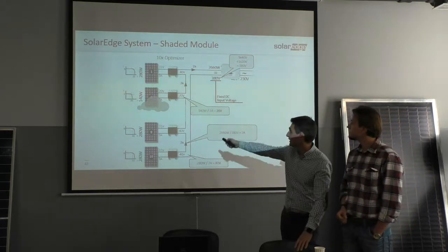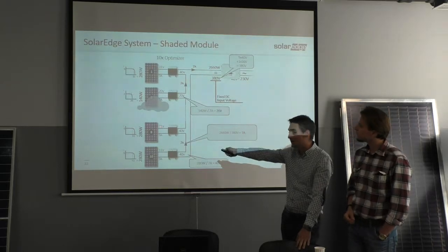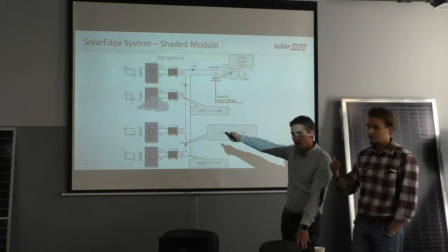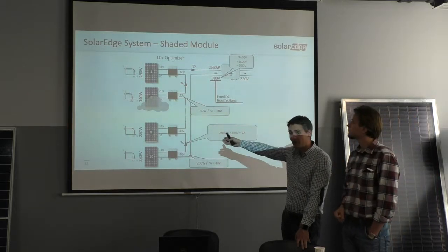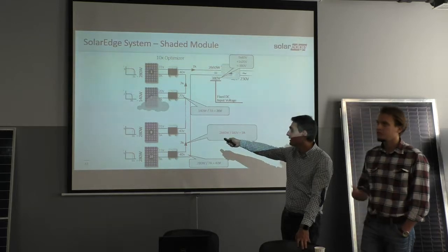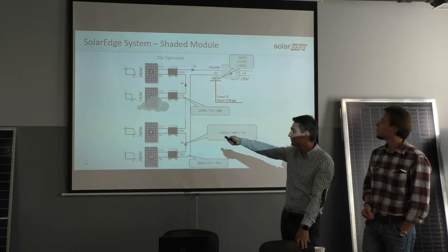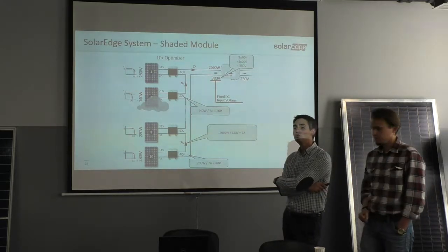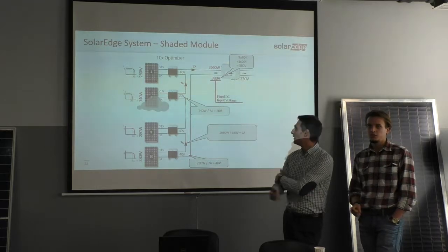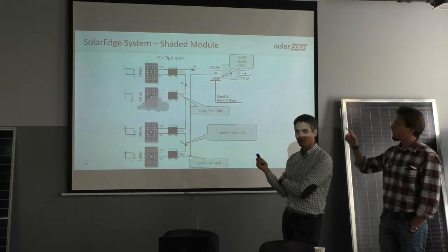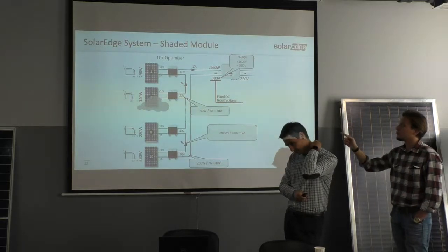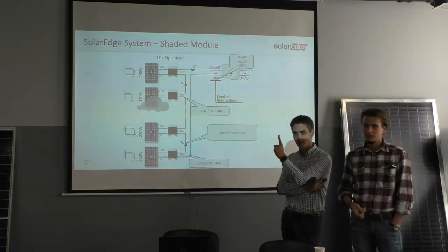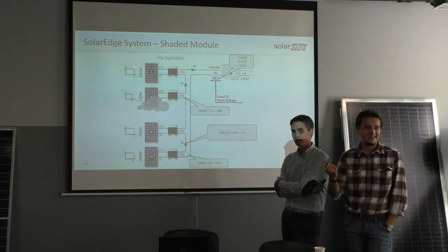The production here will be 31 multiplied by 9 plus 20. It gives us not 310 but 300, multiplied by the lowest amperage, so 7. So 2100. Compared to SolarEdge, which would in any case give 2660, that is 30% of difference, because one module is 30% shaded.